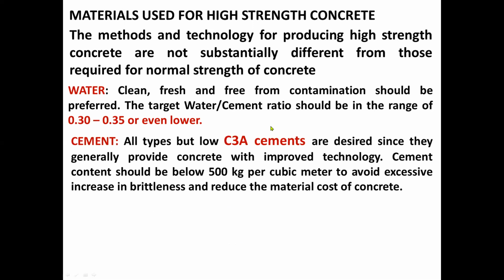Cement, all types but low C3A cements are desired since they generally provide concrete with improved rheology. Cement content should be below 500 kg per cubic meter to avoid excessive increase in brittleness and reduce the material cost of concrete. So hindi pwedeng cement alone lang. Kailangan meron tayong mixture na aggregates. Kung hindi, mas lalong magiging brittle ang concrete.